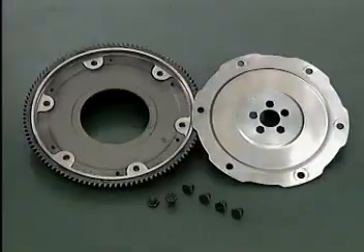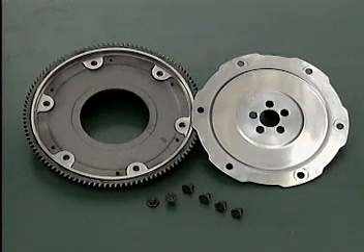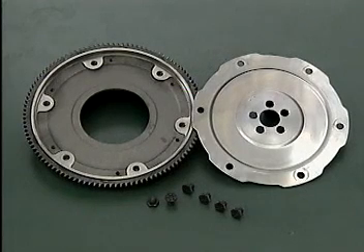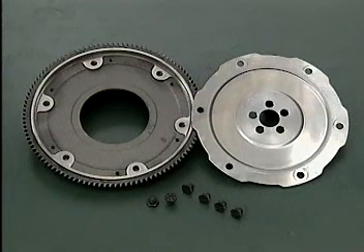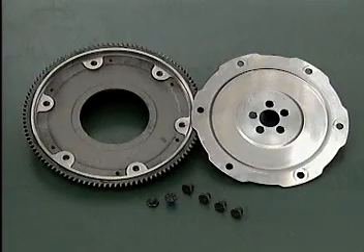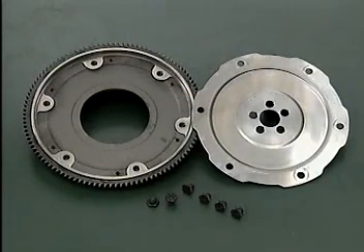The conventional solid flywheel, previously used with the 1.5 liter and 1.8 liter engines, has been replaced with a new flexible design. With this design, the crankshaft and flywheel mass are loosely coupled together using a flexible plate. This new design allows some types of powertrain noise to be tuned out of the range of the human ear. During normal service, the plate should never be separated from the flywheel.